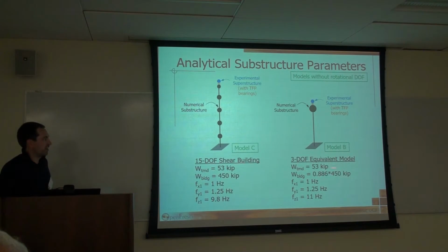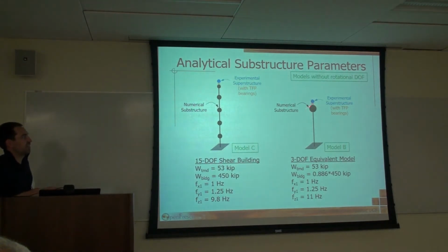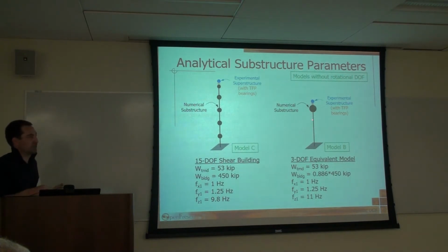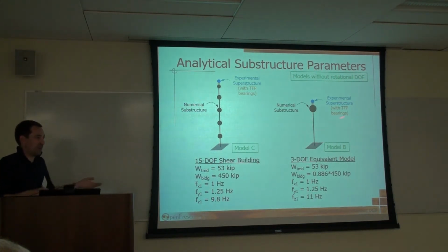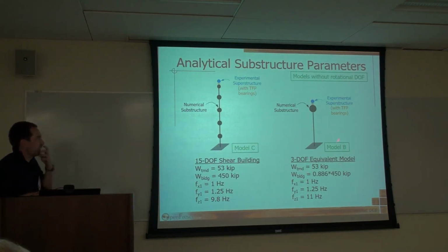In our numerical simulation, our mass or weight is really big compared to what the tuned mass damper is doing on top of it. So it helps us doing these tests. The other thing that helps us is to have the seismic isolation. It's very, very forgiving in terms of testing, because the modes that we're seeing on the actual test specimen are very well behaved. They're low frequency. And so that's what we did.